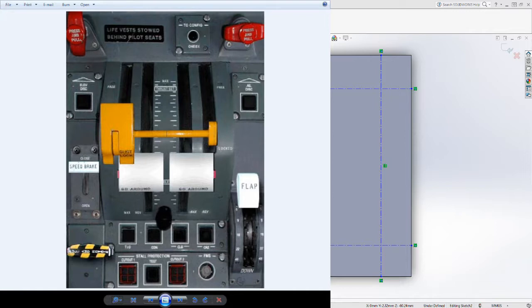The first thing that we're going to do is create the bottom left and bottom right holes, and this is the base panel. It's one panel in a part of usually 2 or 3 panels, depending on what is being made. This one in particular is just 2 panels: a base panel, which is the one that we're making here, and then a top panel, which is the one that's going to have this cutout and all the lettering and text on it.